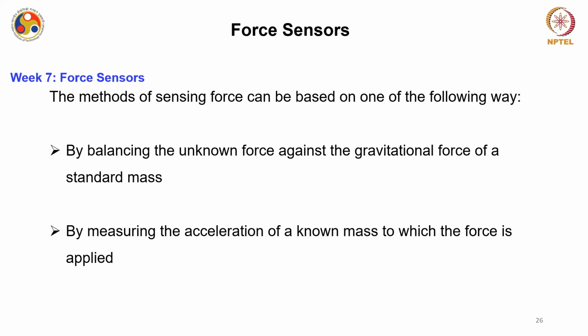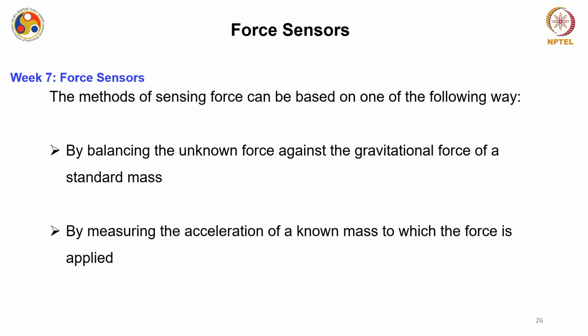Exactly the same thing we have also talked about in the module on accelerometers, where, if you remember, we had a proof mass that was balanced against some external force, and it was calculated by going in reverse, by mass into acceleration. For spring-based devices, mass into acceleration was equated to spring constant into the displacement. Okay.